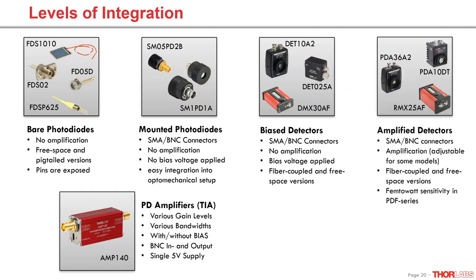The extensive amplified detector series covers the UV to mid-IR wavelength range. High fixed or switchable gain or high bandwidth versions are available here. In all shown models on this side, the photodiode chip is exposed. For detecting higher power levels, an external attenuation must be attached to protect the diode and avoid saturation.